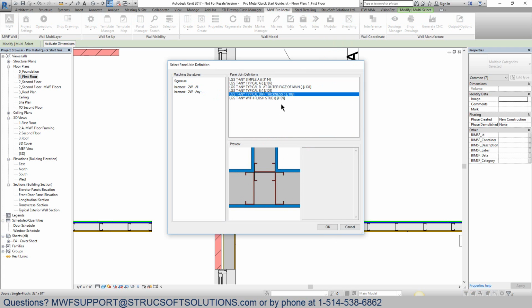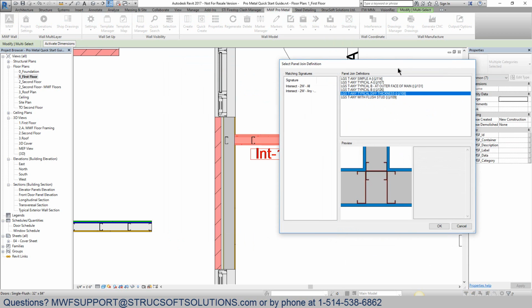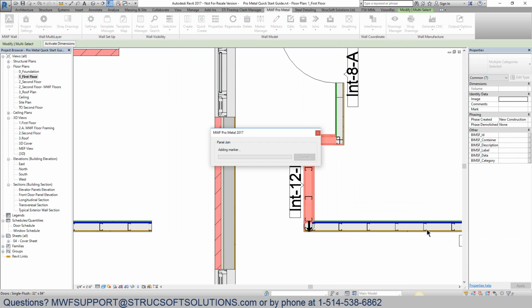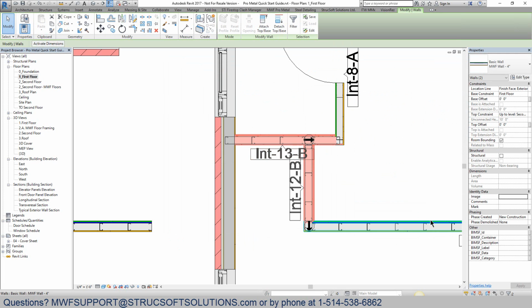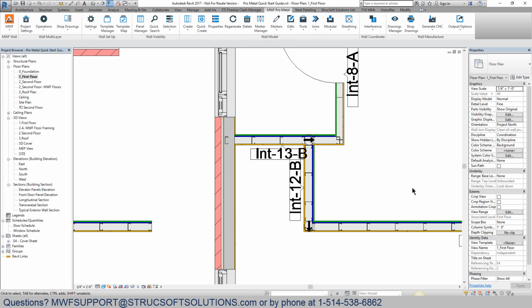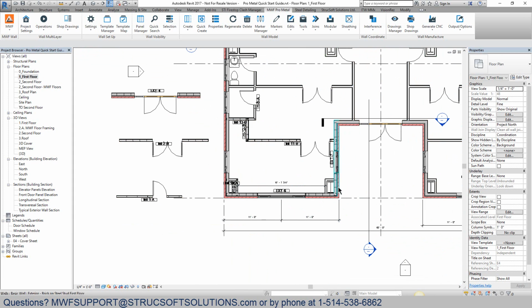These are the same size walls. There we go. So we'll put an intersection wall, corner join right there. So again, we can use the auto join to do essentially a big blanket selection and put in all of those joins. Again, we cover that in those big long trainings.